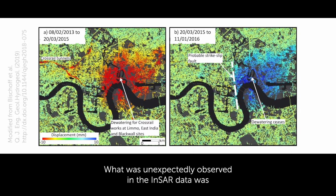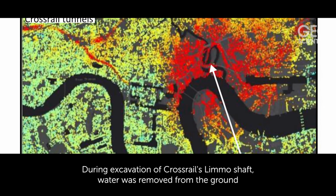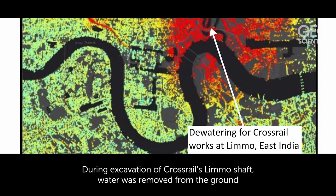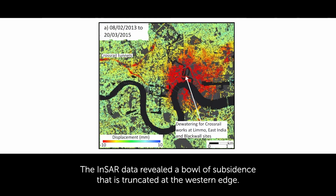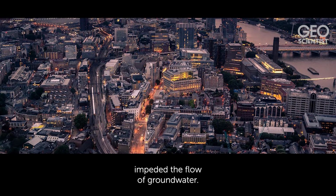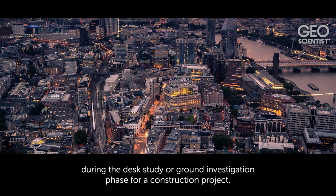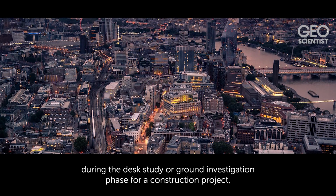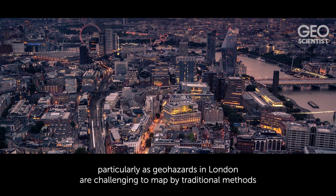What was unexpectedly observed in the InSAR data was the presence of a fault in East London. During excavation of Crossrail's Limmo shaft, water was removed from the ground in a process called dewatering. The InSAR data revealed a bowl of subsidence that is truncated at the western edge. It appears that a strike-slip fault, known as the Lee Valley Fault, impeded the flow of groundwater. The ability to use InSAR to identify these hazards is highly beneficial during the desk study and ground investigation phase of a construction project, particularly as geohazards in London are challenging to map by traditional methods due to the dense urban fabric.